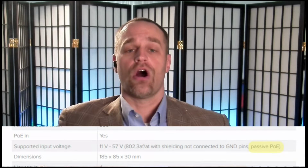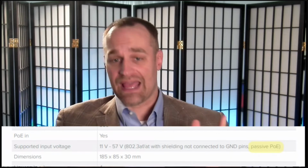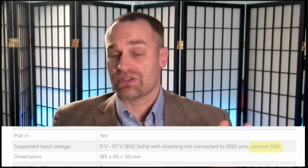Devices that are powered with 24 volt or passive PoE often use mode B, unless some, like Mimosa, specifically call for mode AB. And that's just the most common way to identify whether you're mode A or mode B.